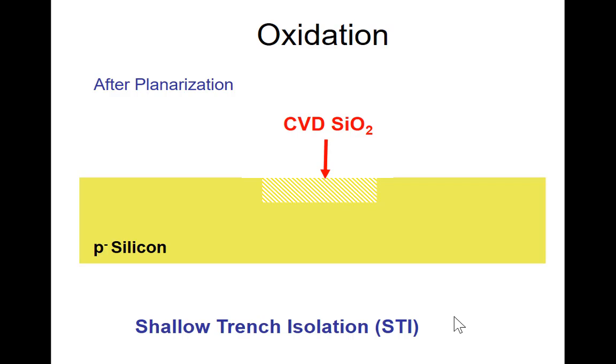You just put a chemical gas into the chamber, with a wafer sitting there, at a different temperature, or two different gases. Then some chemical reaction happens, and some solids form, and then they just drop down onto the wafer. So this is the process.